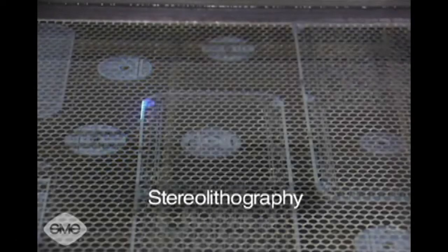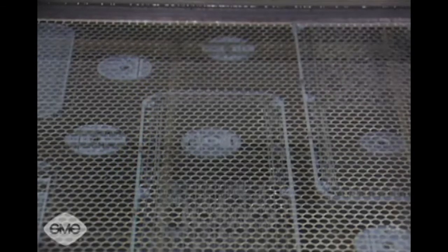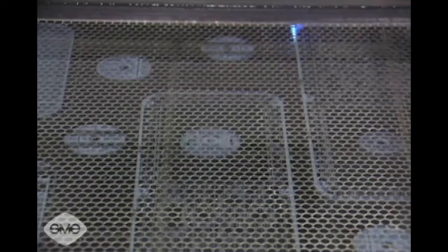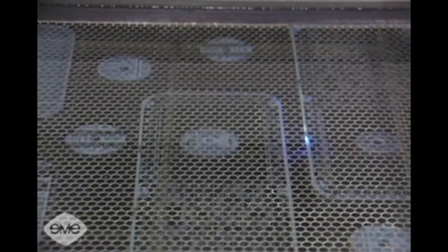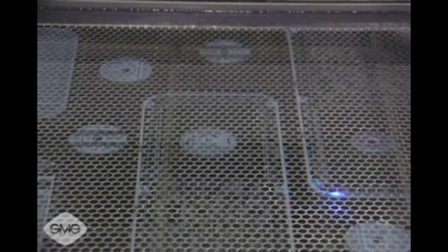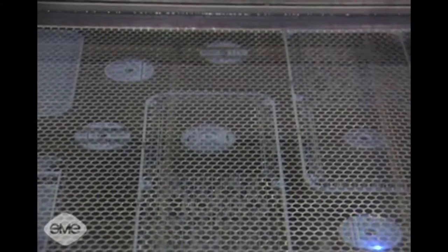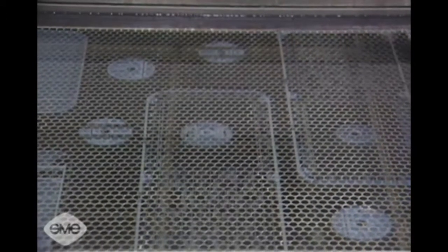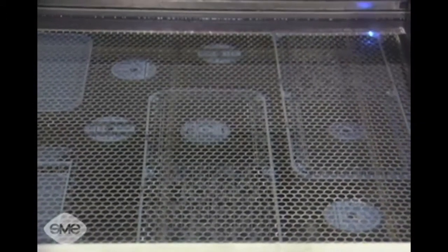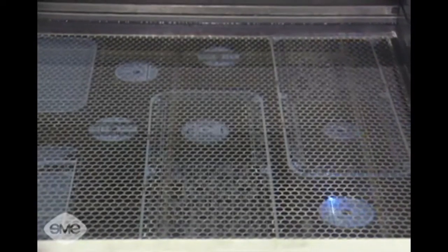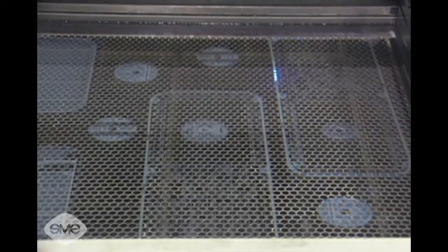Stereolithography, first of the rapid prototyping technologies, is a liquid-based process for making models. The models are built in layers within a reservoir of a liquid, thermosetting, epoxy-based photosensitive polymer by selective curing with the ultraviolet light from a focused low-power laser beam.